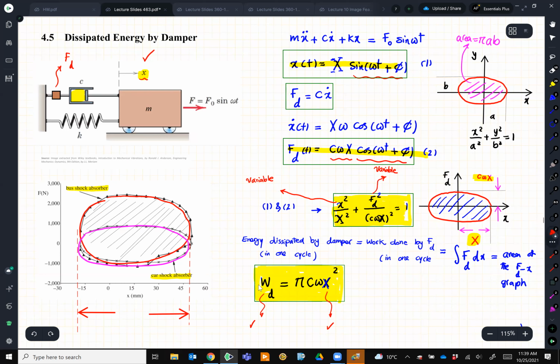And that's the amplitude of vibration. So then they can estimate the damping coefficient C for this shock absorber to compare it with what the factory claims. And usually they do this test every once in a while because the damping coefficient is changing. After, let's say, 1 or 2 years, the damping is not going to be like new. The damping changed, so they need to check whether there is any issue with the damping or not.